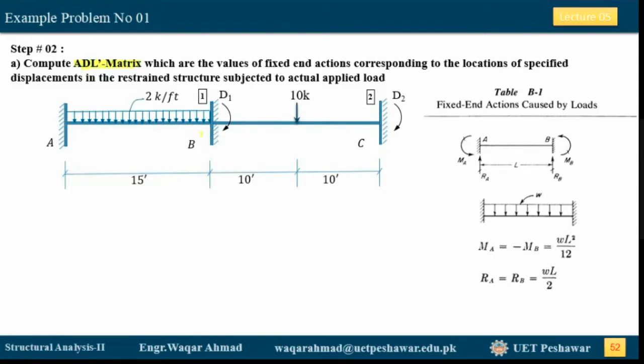So it means that, in a similar way as this 2 kip per foot load and this 10 kip load are applying some effects on our structure, causing movements and shear in our structure, the 0.002 radians rotation at this support also induces moments.